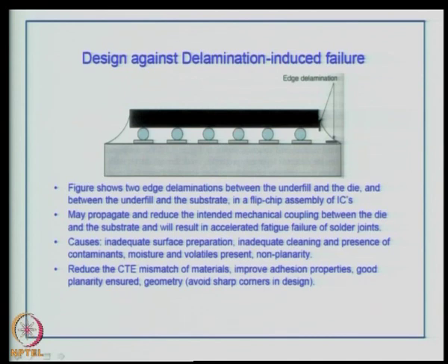Then again you have design against delamination induced failure. This is very typical of flip chip kind of a connection where an underfill is used, and you can also have cracks in the underfill close to the edge of the chip or close to the edge of the PCB.